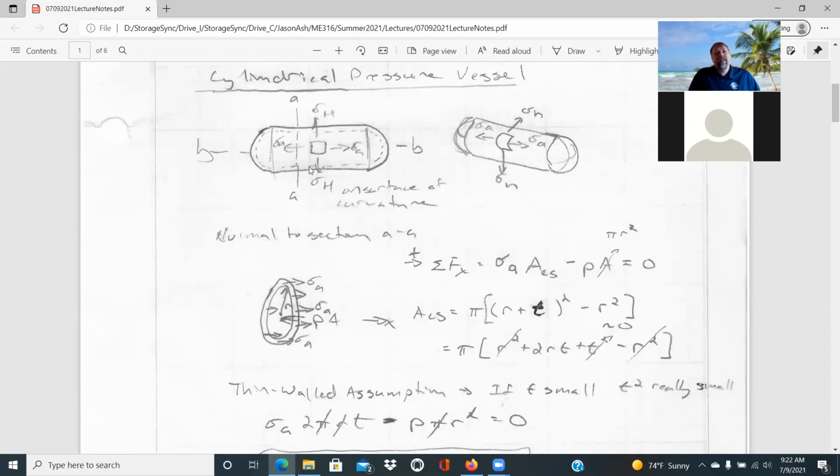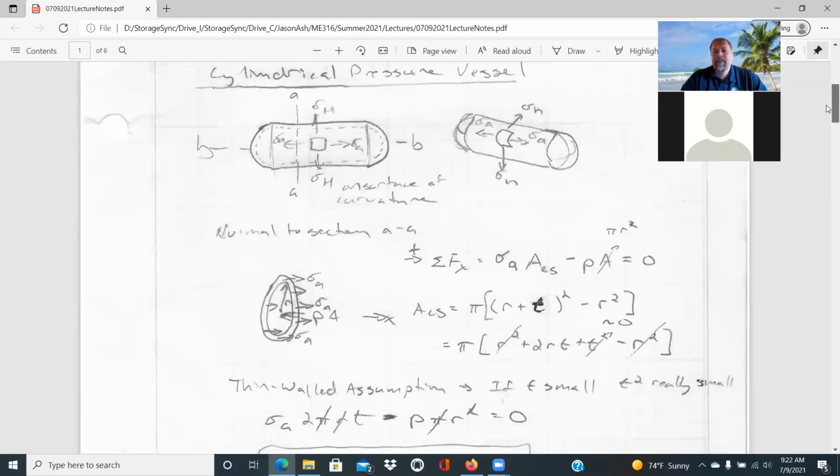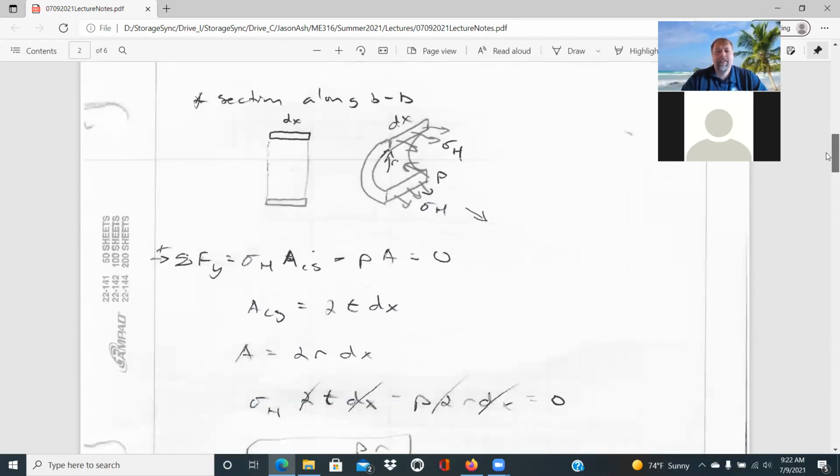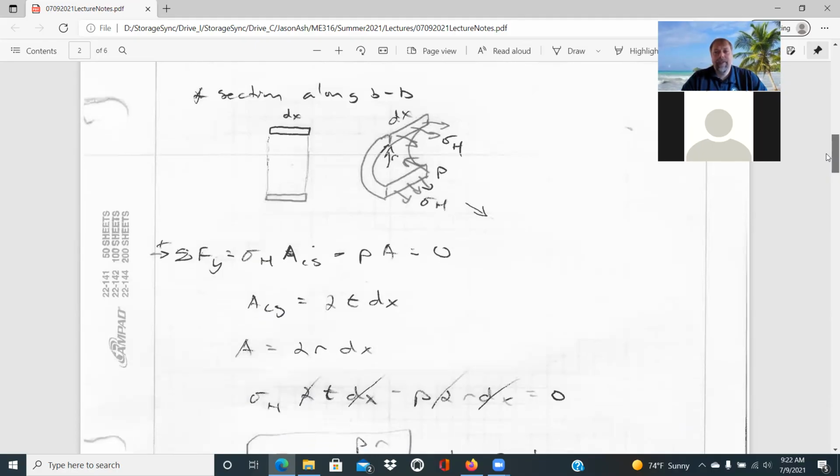But that gets more into that concept of fracture mechanics and looking at the theory of elasticity approach for thick-walled pressure vessels, introducing that leak before break design for pressure vessels. I think as I talk through this stuff, as we move into the next couple weeks, I'll probably pull up some photos so I can show you those types of failures for pressure vessels.